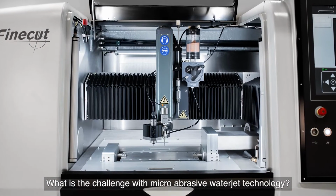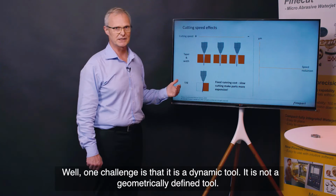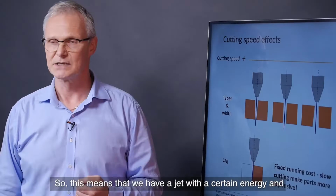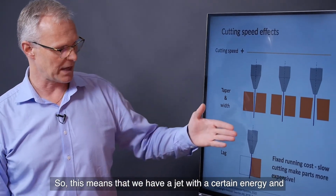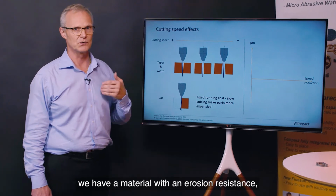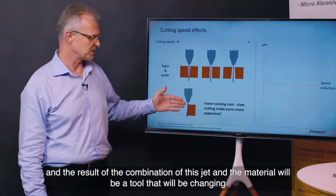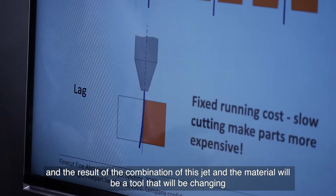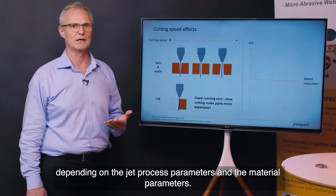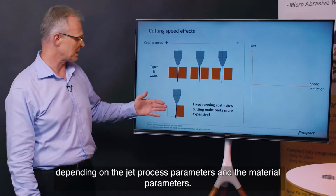So what is the challenge with abrasive waterjet technology? Well, one challenge is that it's a dynamic tool. It's not a geometrically defined tool. So this means that we have a jet with a certain energy and we have a material with erosion resistance. And the result of the combination of this jet and the material will be a tool that will be changing depending on the jet process parameters and the material parameters.